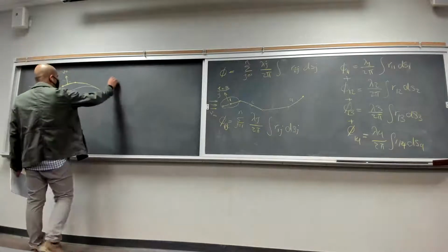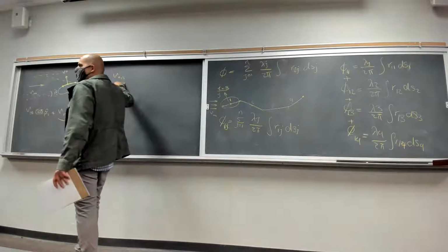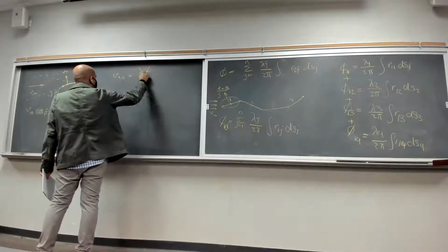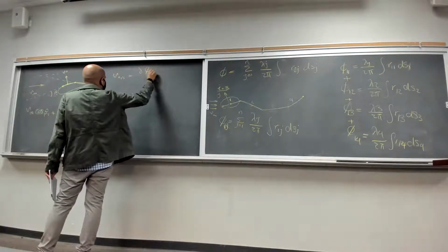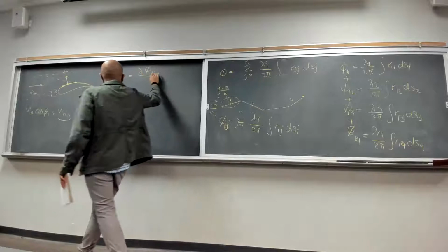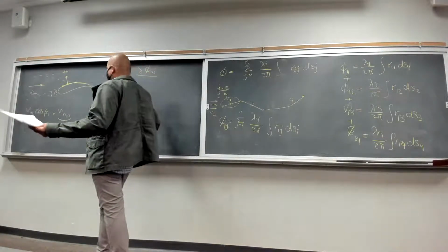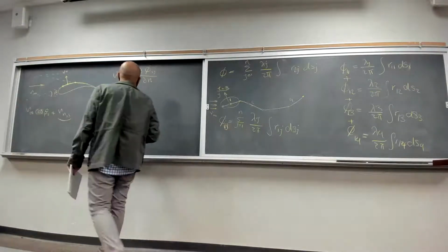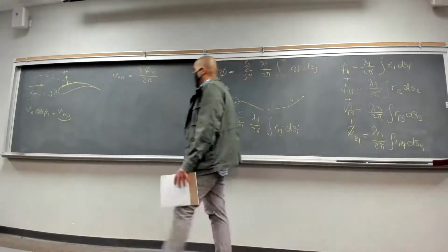So this V_n,s, where n is normal and s refers to the source panel, is going to be the partial of phi for that specific panel, panel I, the potential that is induced on panel I by all of the other panels, divided by the derivative with respect to n.